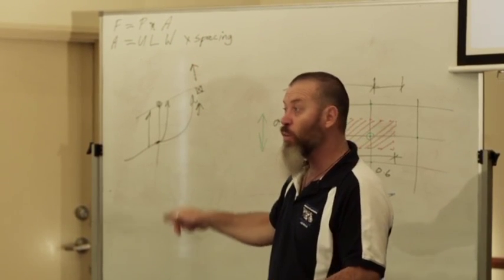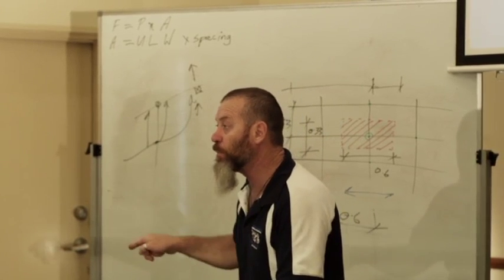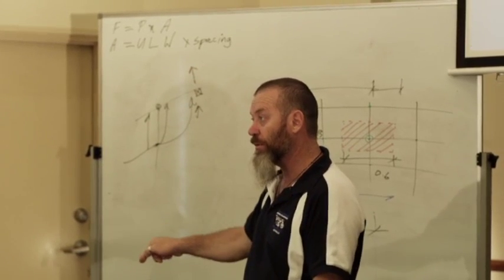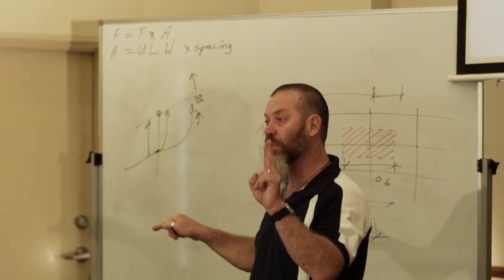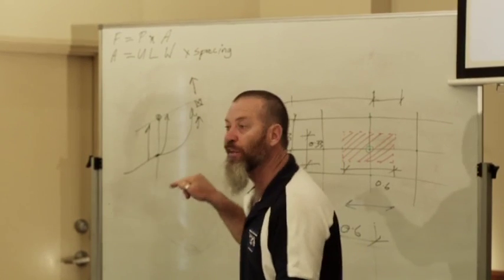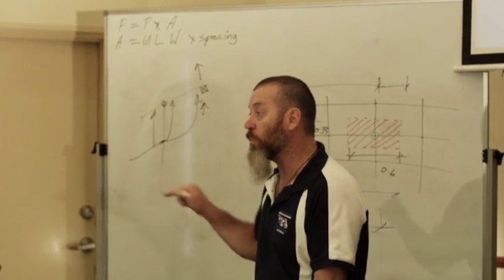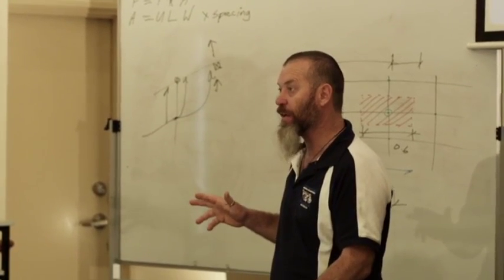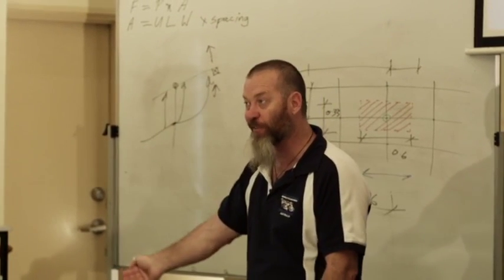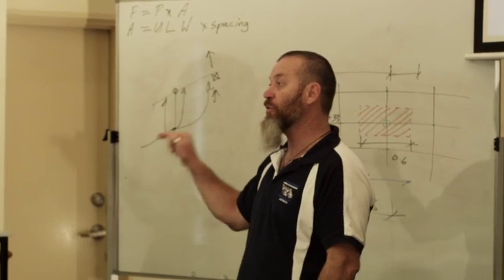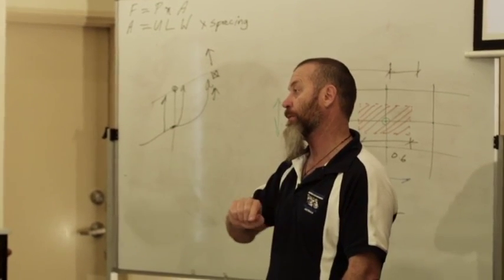Once it hits the bottom plate, the load still continues down, through the floor frame into the ground floor top plate. You follow me so far? Then it continues down the ground floor walls, right down to the ground floor bottom plate.